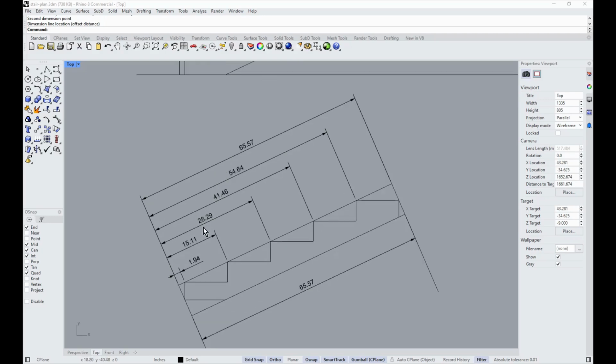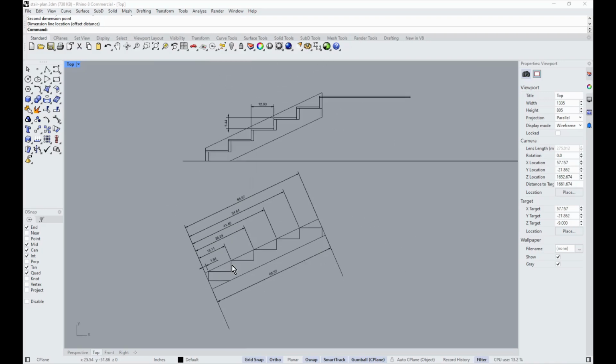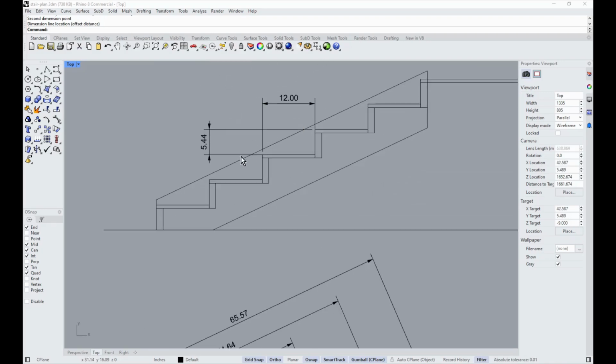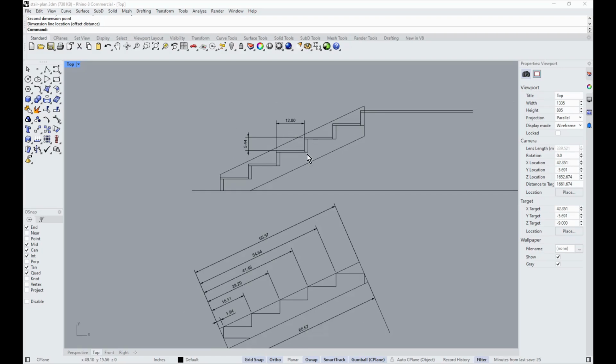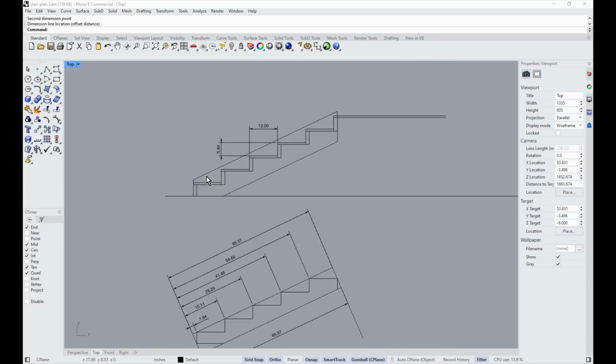And you just do a screenshot of this, print it out on a piece of letter paper, and then you give it to the carpenter on site, and hopefully he can read something this simple and go from there for the stringer. Now for something like this, you could back it up with another one of these stringers right next to it, or you can use a bunch of blocks and nail gun them in there for the setup.